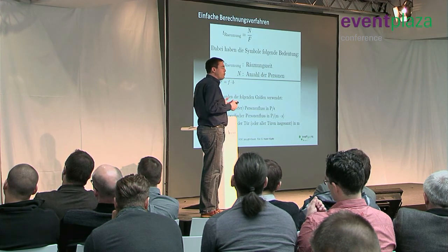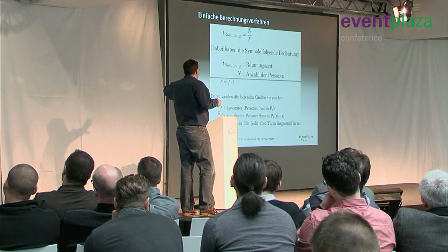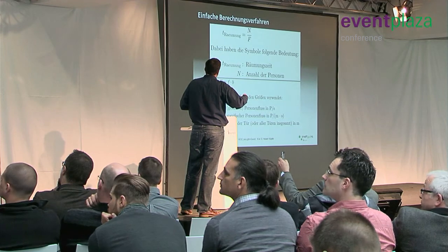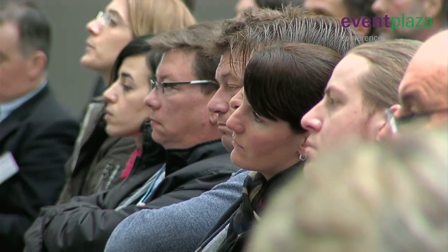We already talked about the flow of people. So if you just want to take a look at the flow of people, let's assume there is an assembly venue, and then you have the limits defined by the width that is limited, and you can assume a constant flow rate. That is 1 person per meter of width per second, which is a very good rule of thumb, and then you can calculate how long it's going to take to evacuate that room. Obviously, provided everything works out quickly.